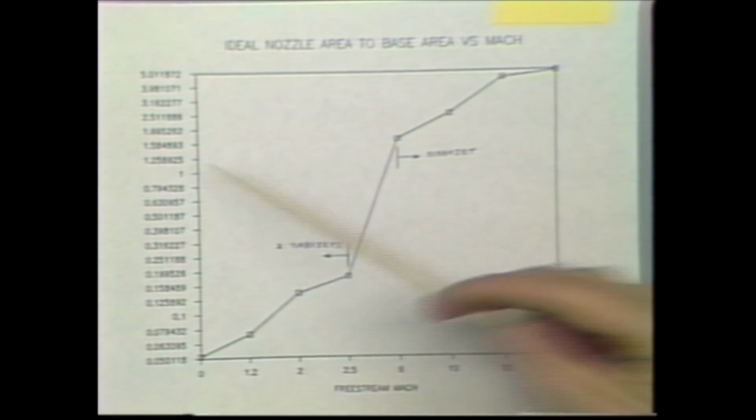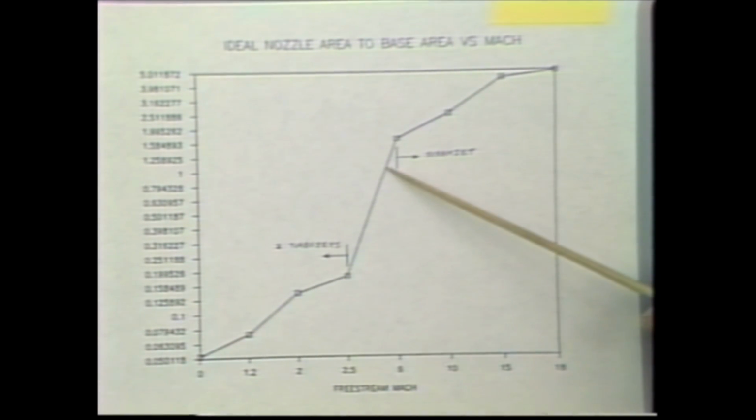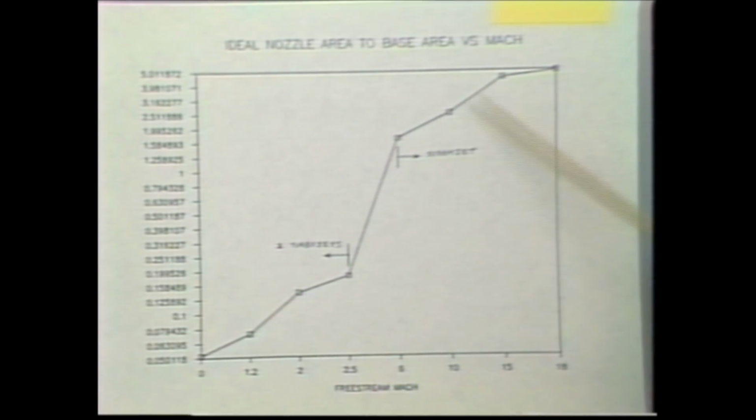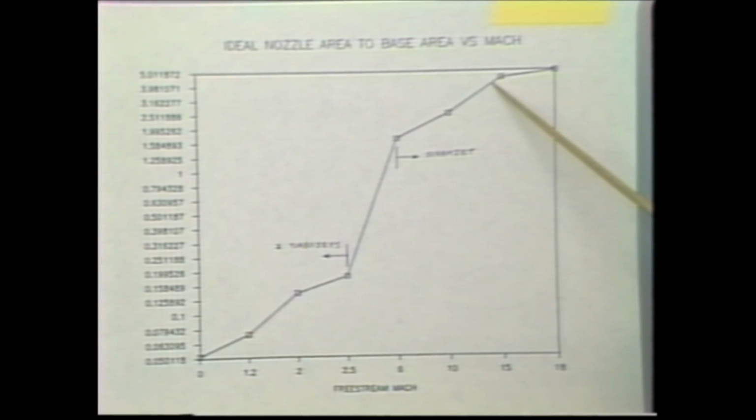Eventually, there's our value of 1, somewhere around the higher ramjet mode, where we fill the entire nozzle, and above that we are actually underexpanded. Even with a large nozzle, we haven't expanded all the way back to ambient conditions in the scramjet mode. This is what drives that area to be as large as it is, the requirement to get as much work energy out of that flow as possible.